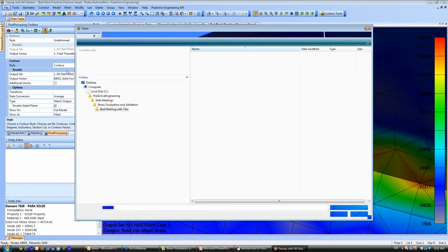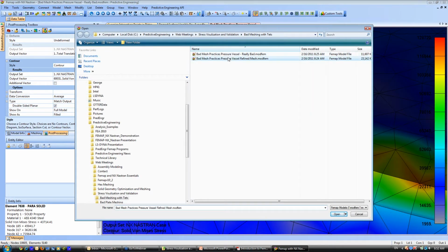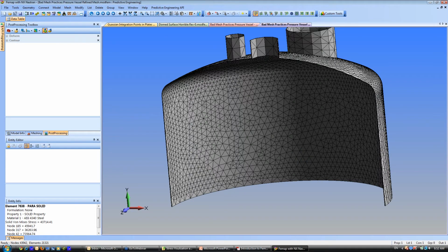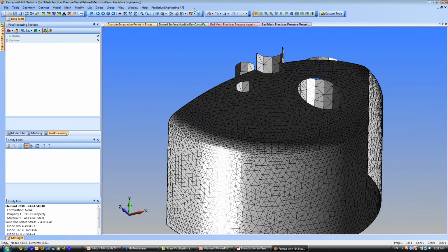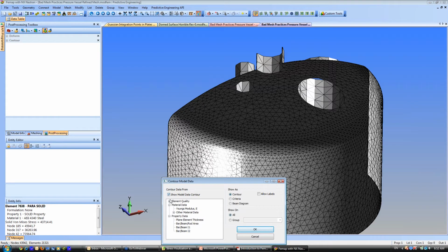And these are powerful, simple tools you can use, because I get people asking, how do I know it's any good? Well, if I have confidence in the loads and everything else, the first order stuff, loads, constraints, dimensions, you know, you're building in inches and somewhere it gets turned into meters, and masses, the weight of the structure. If you get the big stuff done, you can just look at the mesh, look at the regularity, and know it's okay, because you know how things are computed in the background.